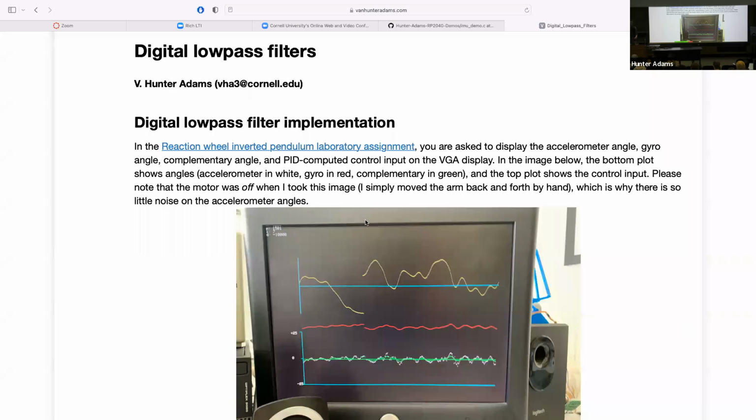If you want more colors, you can, with really quite minor changes to the VGA driver, get yourself 4-bit color as opposed to 3-bit color. And that gives you a nice gradient, which might look nice for a ray tracing project. There's some example, we can talk about that in lab, but yeah, I think that would be a nice thing to add to the VGA driver for something like this.